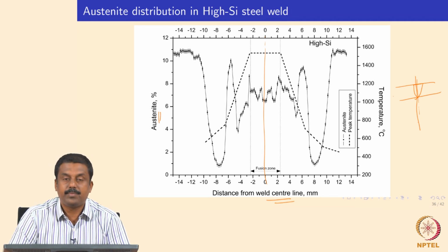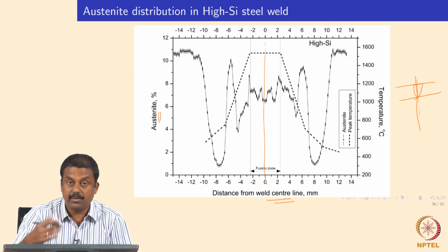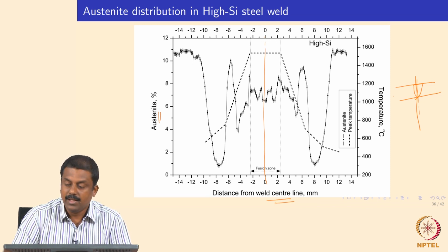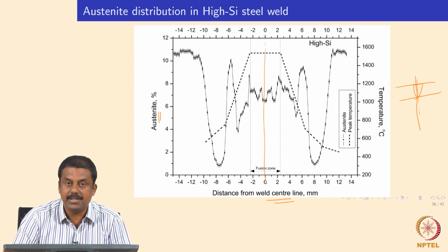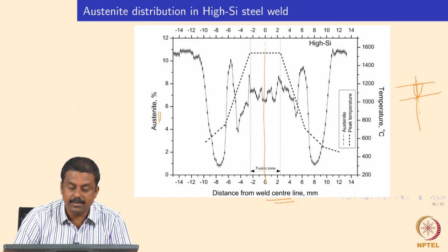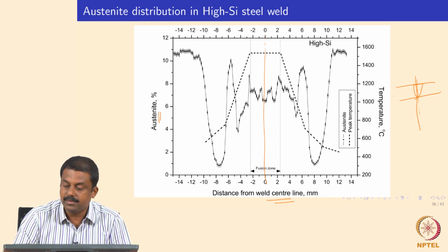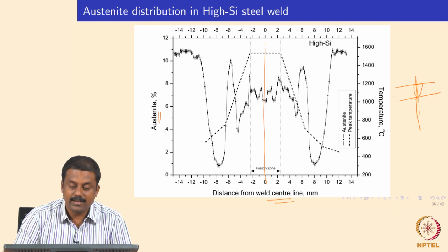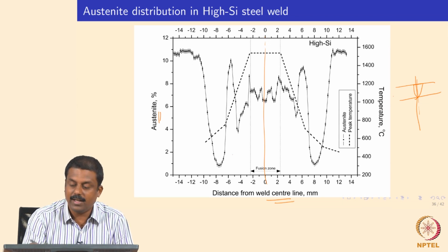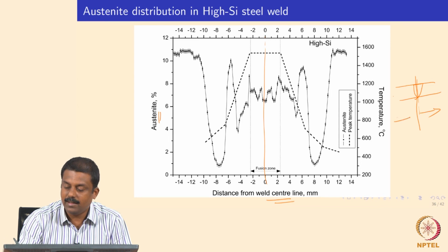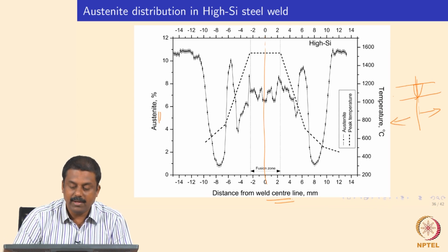containing silicon, using a GMAW bead on plate weld, which I showed you in previous lectures, and you can refer to the figures and identify the weld zone regions in the slides I showed in earlier videos. Now if you look at the retained austenite variation along these lines, it's very interesting to see, right? It is symmetric. If you look along the weld center line from this side and this side, it looks very symmetric, but we will see one by one.